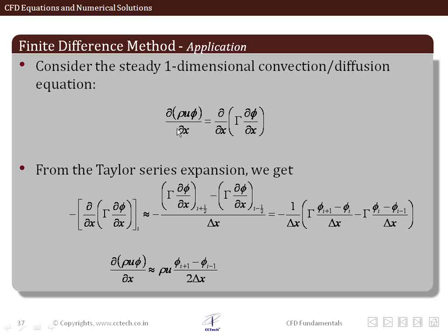But to just demonstrate how the finite difference method can be used for such a convection diffusion problem, we're just trying to see how the convection term can be expressed as a central differencing equation, which is the difference equation we have obtained by applying central differencing around the node i. And the second derivative is applied using the definition which was there in the previous slide.